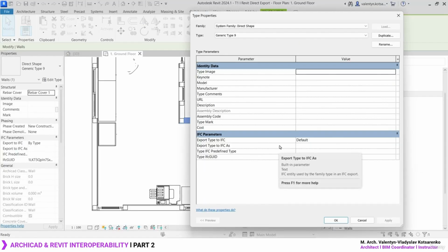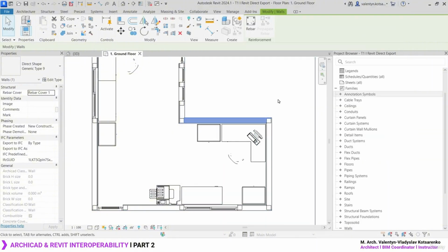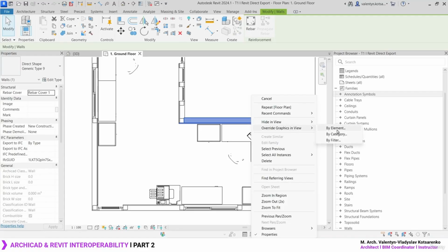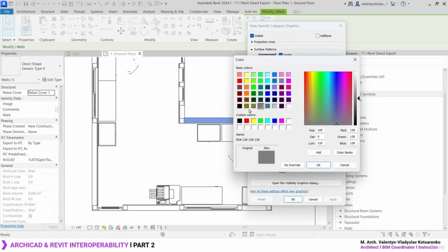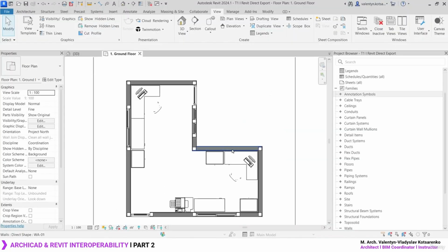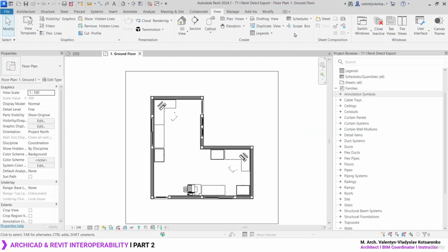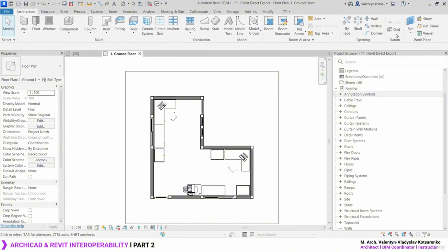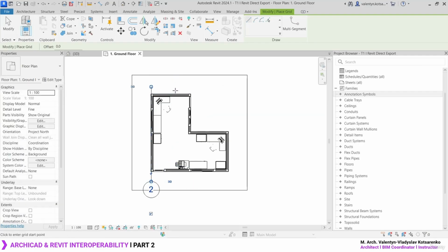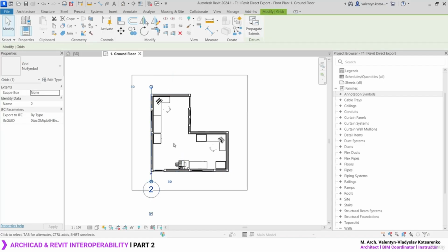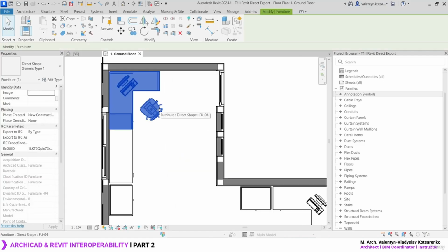So that's the feeling inside Revit. But yeah, we still can, for example, take the wall. We can override the category. Maybe for the cut pattern, we can assign some type of gray color over here. It's just going to take a few seconds. Maybe override this. Maybe proceed with some grids for the project. So yeah, you can still document this to some extent, but it's not as perfect as if you would start the project once again in Revit from scratch.